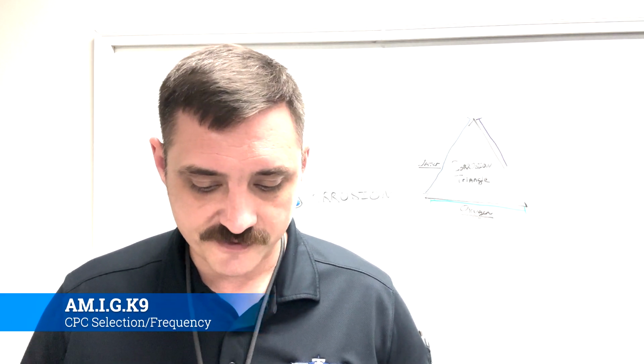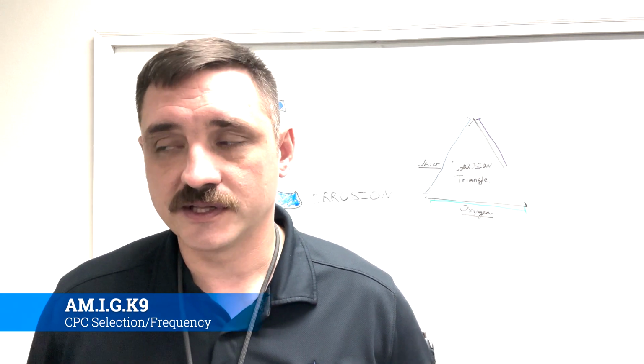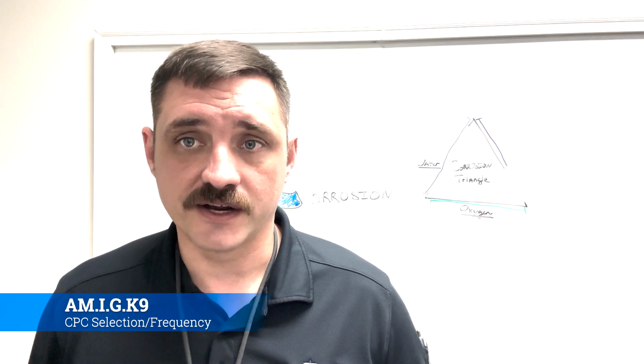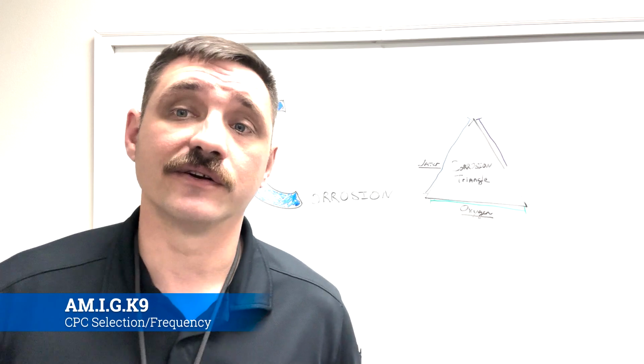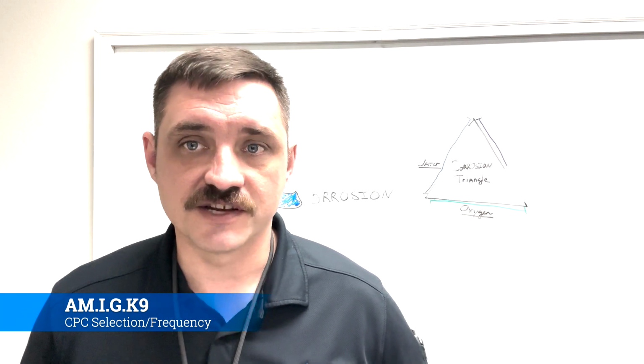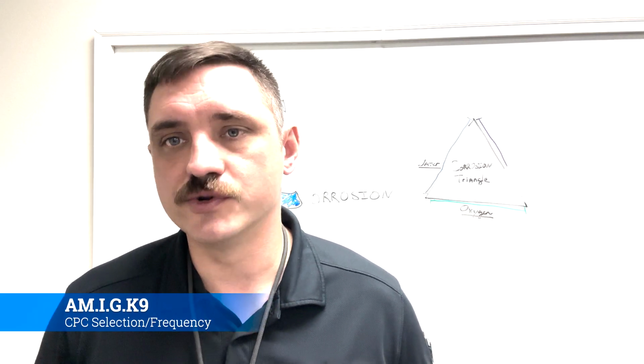Okay, so frequency of inspections is Chapter 5 of AC 43-4. It'll say aircraft operating in a severe environment should be inspected every 15 calendar days. So the way we got around that with the Army, instead of every 15 calendar days, we did it every 10 hours, and we were flying at least an hour a day. So we were actually exceeding the standard on that.